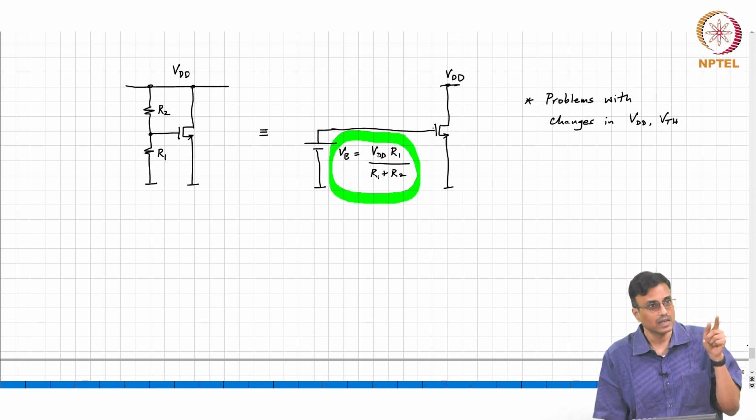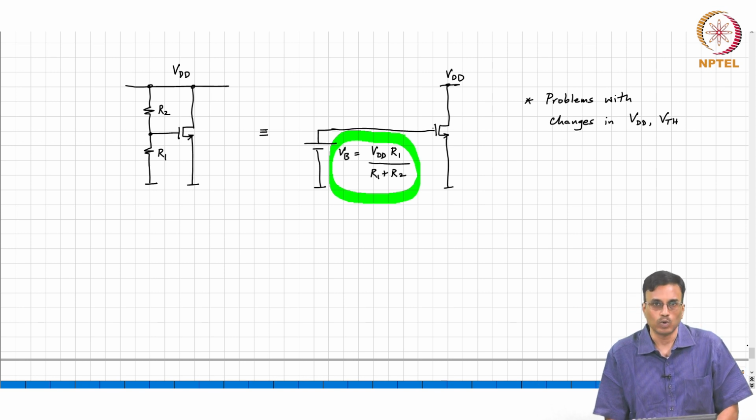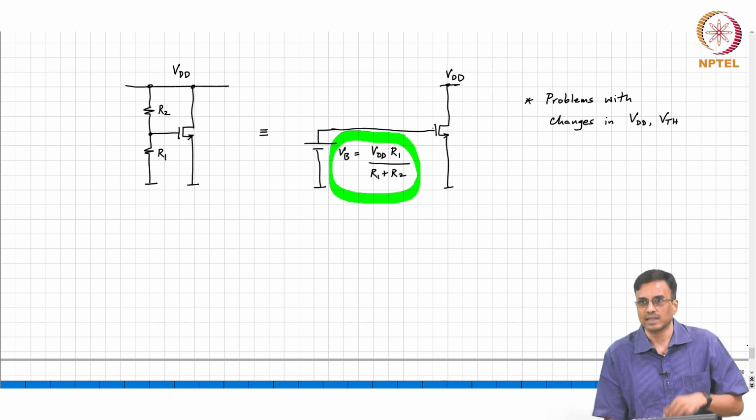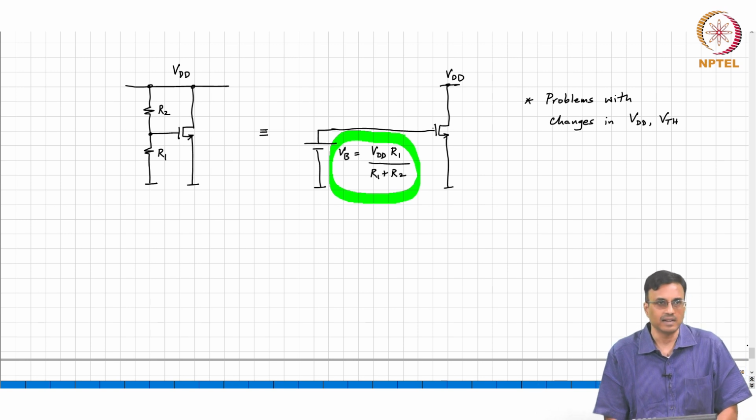What should be the gate source voltage that I should apply so that the current in the drain is fixed? So, if I answer that question, then I will be able to hopefully build a circuit to do the same thing, and that basically will ensure that regardless of the ambient temperature, what the threshold voltage is, you get the desired current Iref in the drain.